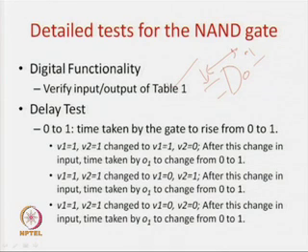If this gate has a very high time delay, obviously the whole circuit, which is composed of so many small gates, will also be slow. If you want minimum delay, or you want to increase the frequency or the performance in terms of the speed of your circuit, these gates should have a lower delay. So, delay is a very important parameter in circuits.